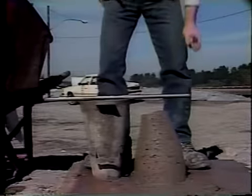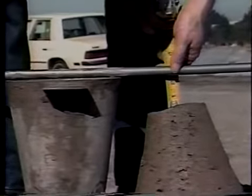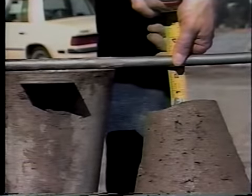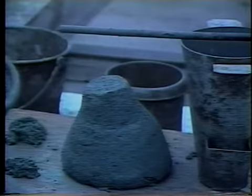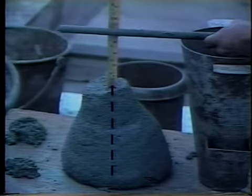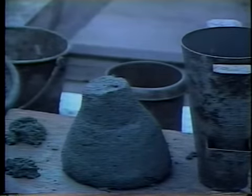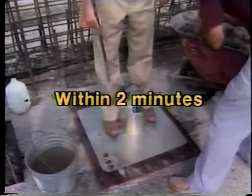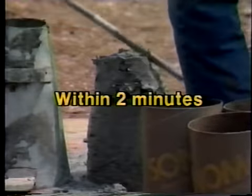Immediately, the tamping rod is laid flat across the top of the cone, extending over the concrete. A ruler or measuring tape is used to measure the distance between the bottom of the rod and the top of the concrete. The measurement should be made to a point that is directly above the center of the bottom of the concrete, not at the center of the top. The entire slump test must be accomplished within 2 minutes, as measured between the adding of the first layer and the measuring of the slump.